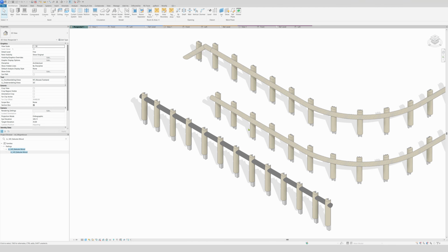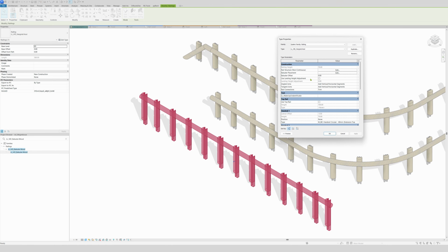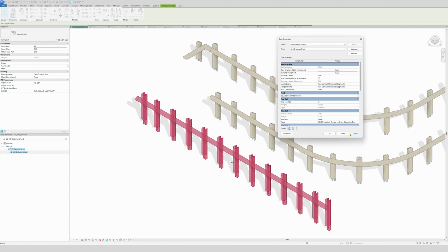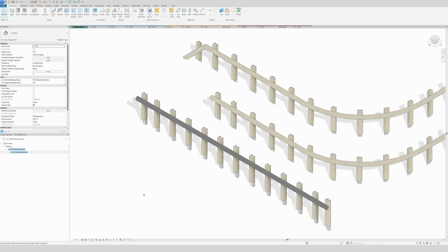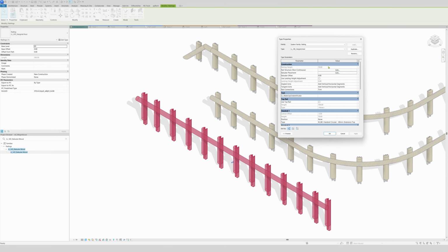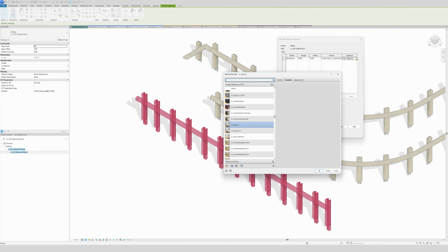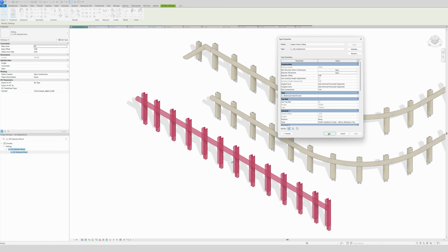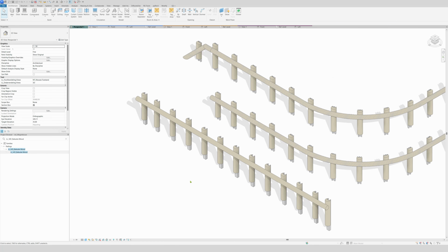Now we need to get the rail an offset so it's like this. Well, we're gonna do that again. We go to our rail structure, edit, then we're gonna give it an offset of 12. I'll just see what it will give, and voila, this is what we want. And now we need to just give the rail a material, and right here under material we have wood. That's okay. Apply, apply, and voila, there is our rail.